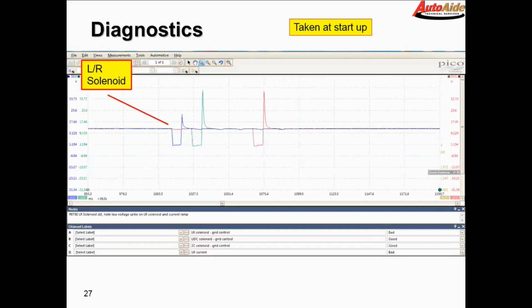Now, typically, you're going to have 1 or 2 problems here. The source voltage is the same. You can see that because all solenoids are drawing about the same amount of voltage down through this section. It looks like they're all being grounded, but when they let go, the inductive kick isn't high enough. So what could do that?